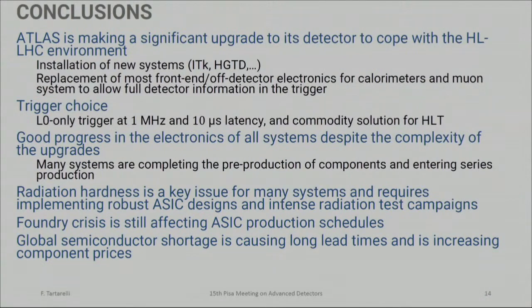So, conclusion: ATLAS is making a significant upgrade to its detector to cope with the HL-LHC environment. The trigger has been chosen. There is good progress in the electronics of all the systems despite the complexity of these upgrades, and many systems, as I showed you, are entering pre-production or production. The radiation hardness is a key issue for many systems, and so requires implementing a robust ASIC design and doing an intense radiation test campaign.